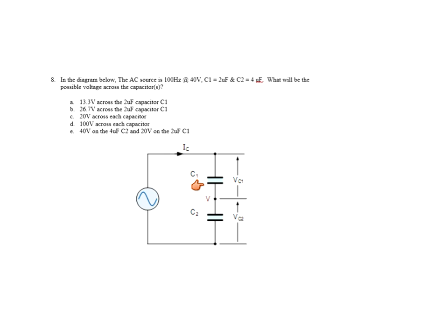Okay, well I have 40 volts applied, don't I? So these two voltages added up have to be equal to 40 because that's Kirchhoff's voltage law. Let's look at these answers. Well, can I have 13 volts on the 2 microfarad? The 2 microfarad is here, and the total voltage is 40. That seems like less than half.